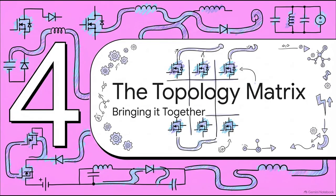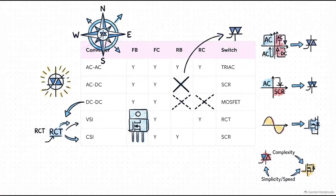Section 4. The Topology Switching Matrix. Let's bring this all together. Now, this master framework brilliantly illustrates the entire landscape of power electronic switching in one single view. Just scan across the matrix. AC-AC needs all four states, so we use a triac. AC-DC drops reverse conduction, so we shift over to an SCR.